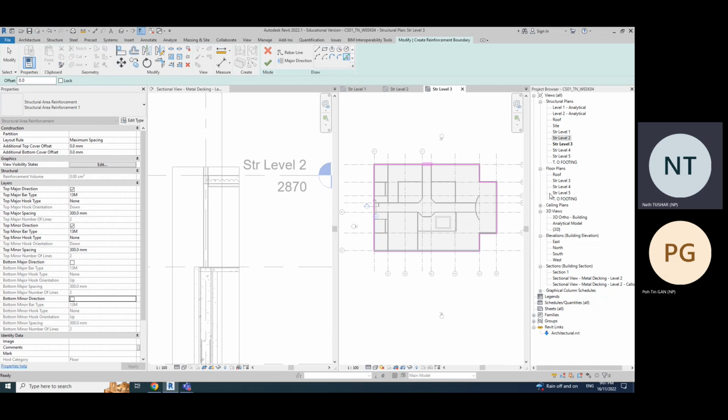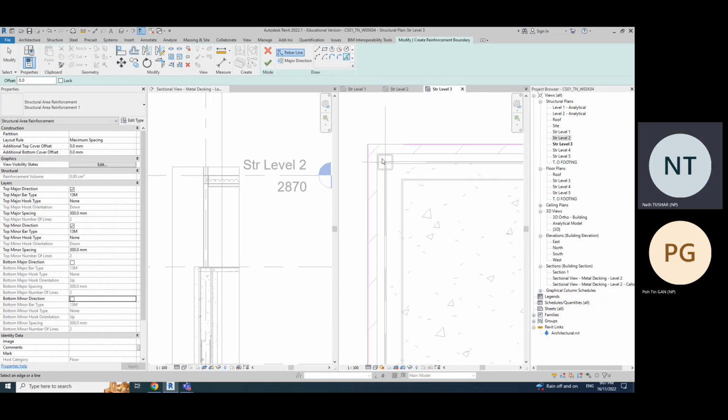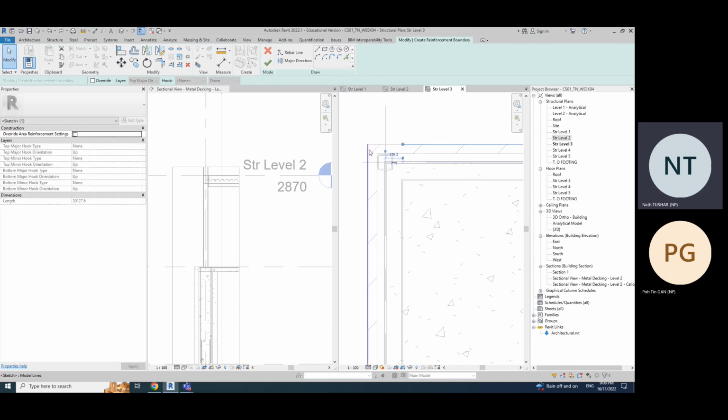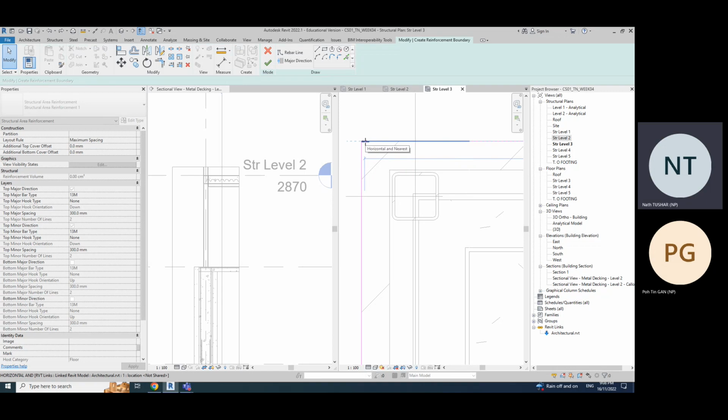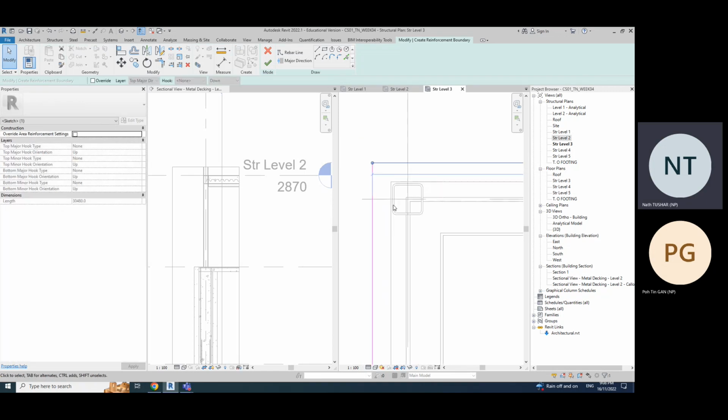Remember this command? So what happened is, this is the line. Oh, sorry, highlighted lines. Need to delete one. Okay, so this is the line, and this line does not close. There is no closed loop between these two lines. There are two options I have. One, I can select this line, select this blue dot, and drag like that till it meets this one.